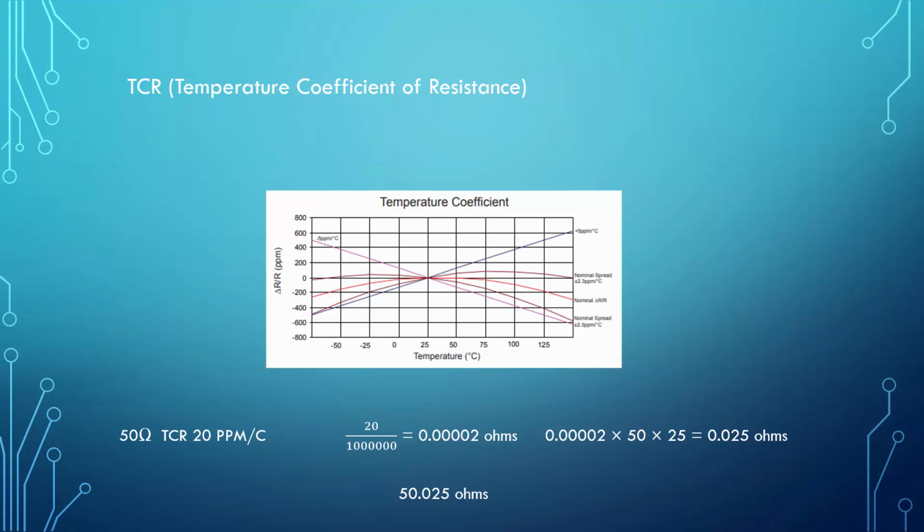So if you assume that we are going to pass this current through a 1 kilo ohm resistor, and if your resistor has a high TCR, you're gonna have some problems here. Because if temperature changes too much, you can't have precise sensing, right? But in your typical applications, for example, pull-up resistors or voltage divider resistors, it's not a very important parameter.